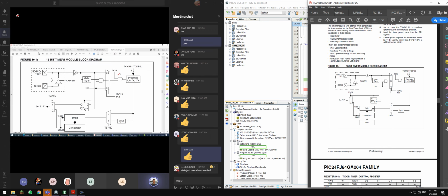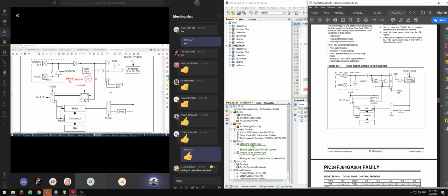So this is just to switch on the timer. This one is external; we are going internal using 8 megahertz. Divided by 2 is 4 megahertz, so it's 0.25 microsecond. Every tick is 0.25 microsecond. This one is just for you to choose. Let's say the tick is starting from the value 0, 0, 0, 0.